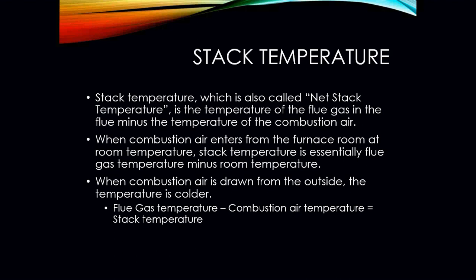Our stack temperature, which is also called net stack temperature, is the temperature of the flue gas in the flue minus the temperature of the combustion air. When we hear combustion air, we're thinking about the temperature of the room itself that this furnace is in.